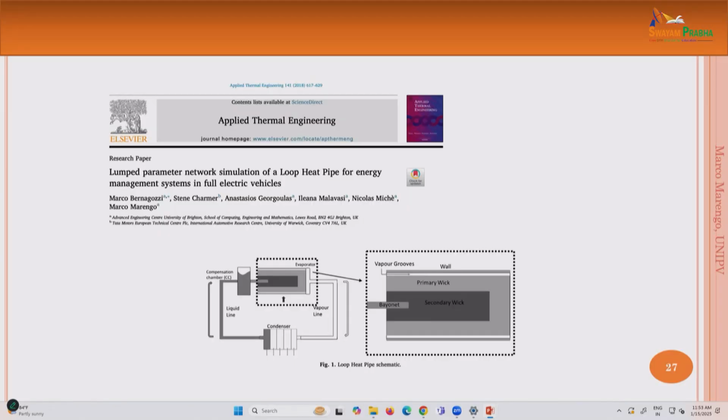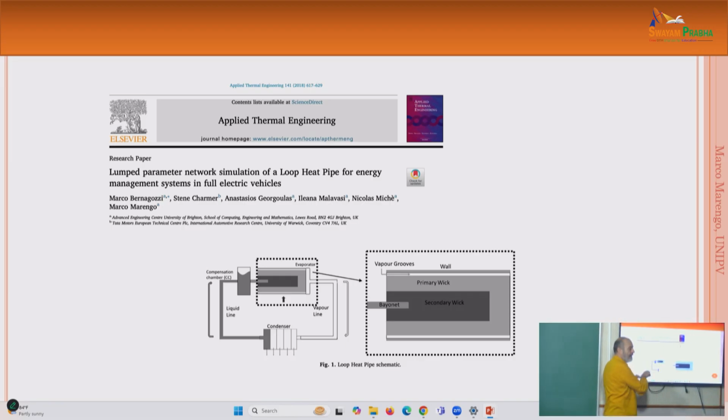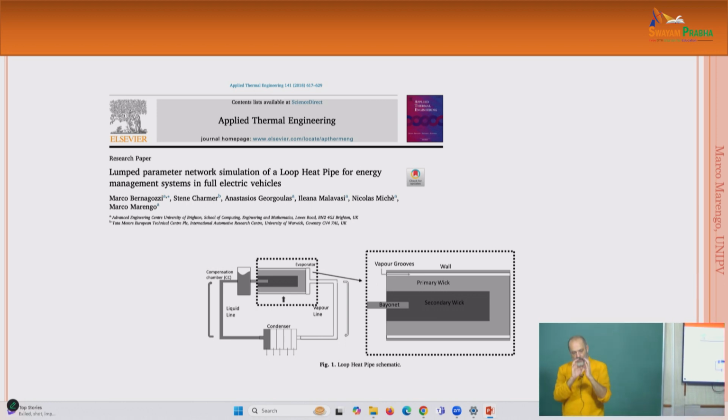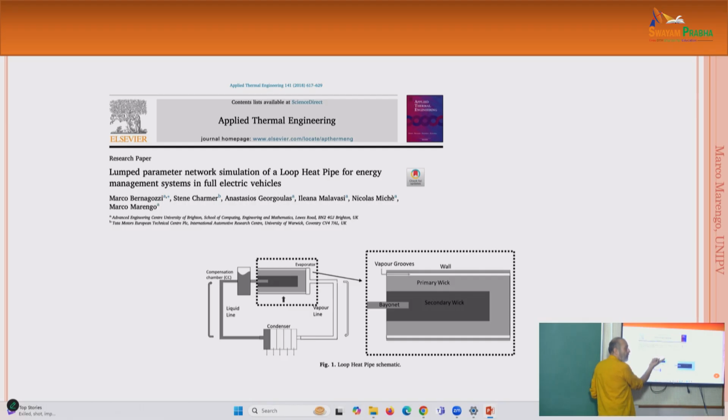And you can see from this graph that we plotted the compensation chamber at a given distance from the evaporator with the bayonet, but in fact it can be together, in the same piece. We may have a room, a space for the liquid to enter. And this avoids the dry out, because if the liquid is going inside, there is a kind of reservoir for the liquid. Otherwise, we may have a problem, because the critical point is that we need to be sure that the liquid is going back, is pushed in this direction, okay?